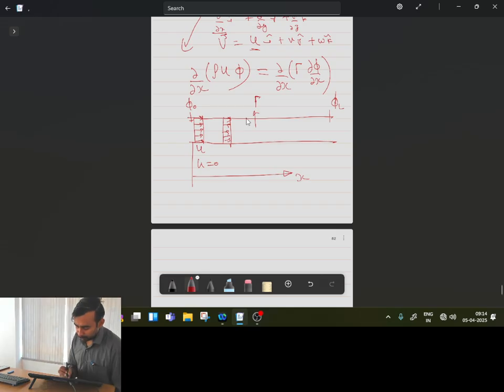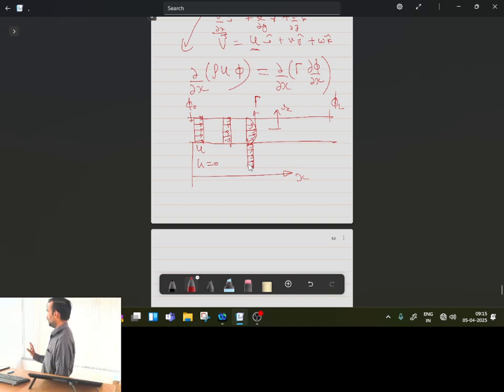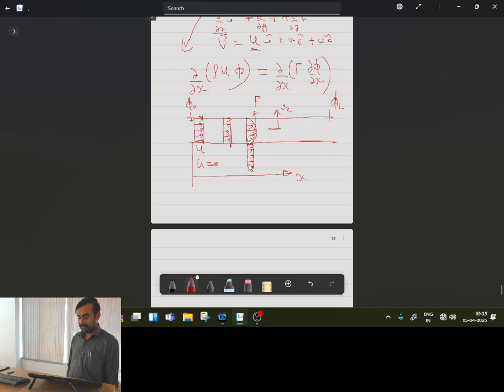There can be no slip condition in an actual flow scenario where your interest can be to understand the complete velocity profile, because of the real nature of the fluid. But here we are assuming that whenever we are analyzing this flow problem, we are not considering the variation in the radial direction. Our entire interest is to see the variation in x direction. That's why even if in a physical situation there is this type of velocity profile, I am considering its average representative value at that particular cross section. Is this one clear? All are clear with this idea?